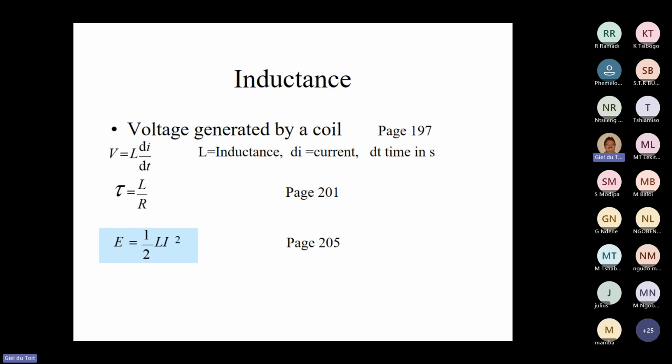And then lastly, how much energy can an inductor store? Remember I said we can store energy with an inductor. So the energy equals half L i squared. So 0.5 times L. If L was 1 Henry, then it's 1 times the current. And if the current in the above case was 10 amperes, let's calculate the energy. 10 amperes squared gives me 100. 100 times 1 Henry is 100 joules, times 0.5 for this half there. So it will be 50 joules for our case.